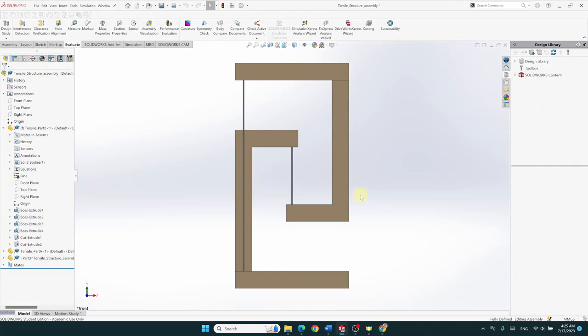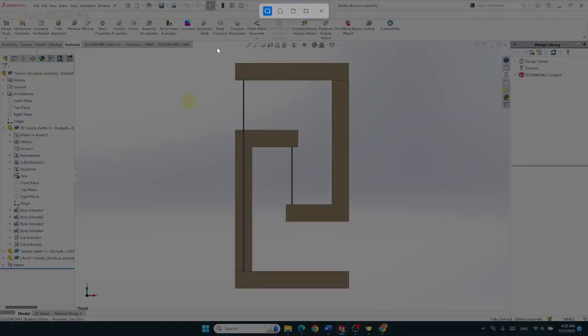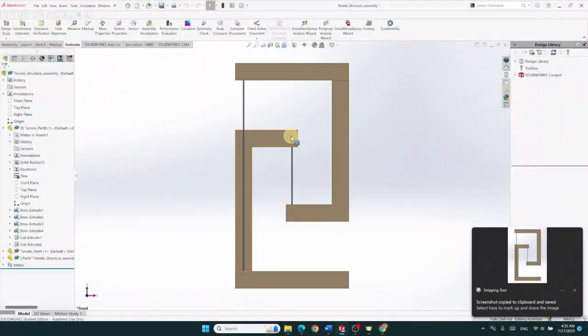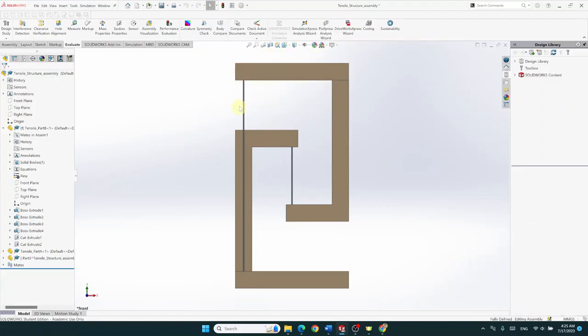I recommend that you take a screenshot of this one. Let me show you like this. Take a screenshot, include it in your report, and show me where the weight is. Is it there? Is it there? You show me the tension from the rope. This one will go up because the rope is up. This one will be down because the rope is down. Remember, the rope can only pull. And show me the weight, and show me some moment equations, like about this point A, the weight at G, this point at B, any other point maybe at C. Show me the different moment equations and how they could balance each other.